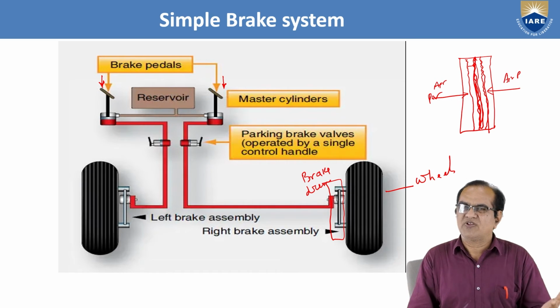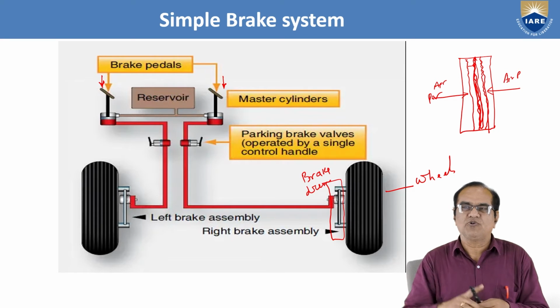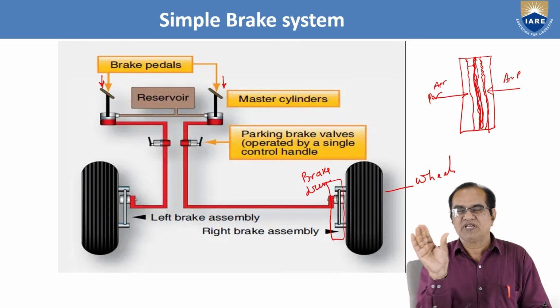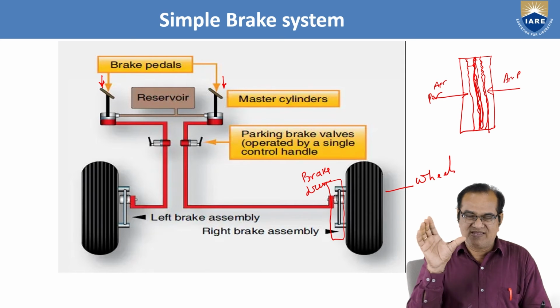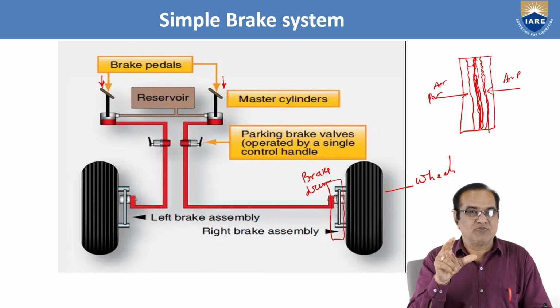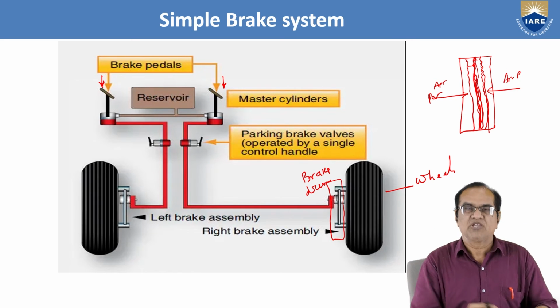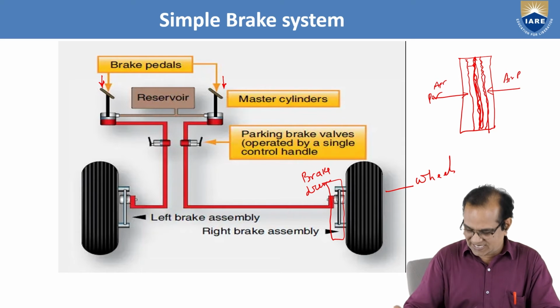So this is the basic principle of any brake system, and in this way the brake systems are working for aircraft, for your vehicle, for your car, for anything, scooter, bike. Everywhere the basic principle is the same. If you see in your bike also, you can see one disc. In that disc some shoes are there, brake shoes are there. These brake shoes are the frictional material, and by the pressure of the hydraulic or the pneumatic, they are pressurized. Once we are doing like this, you are getting all this pressure and your wheel is getting braked.